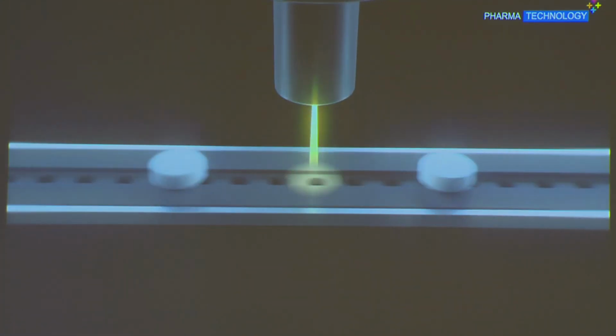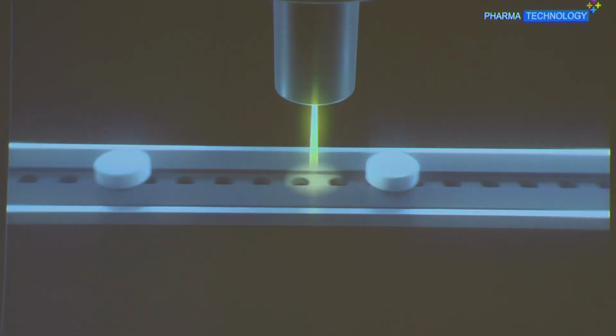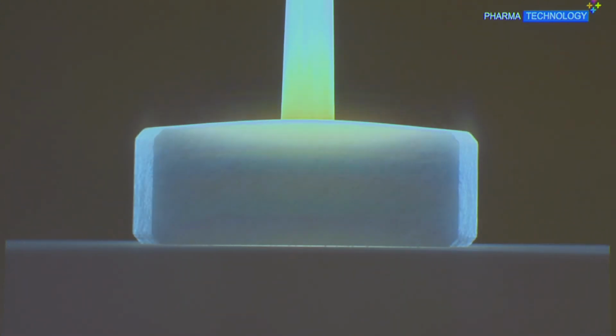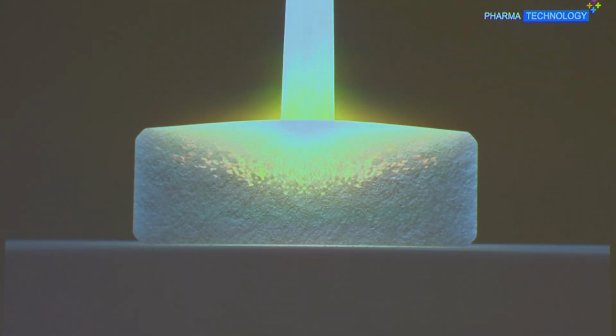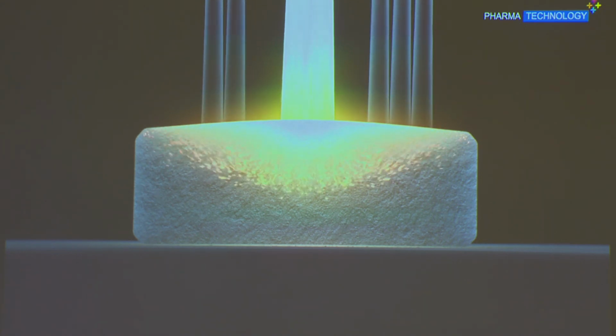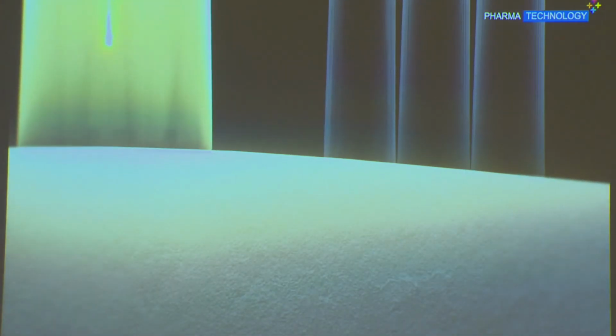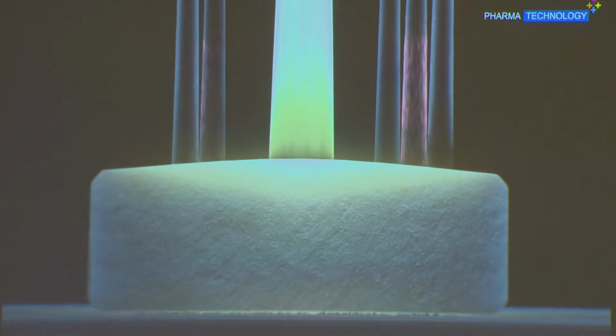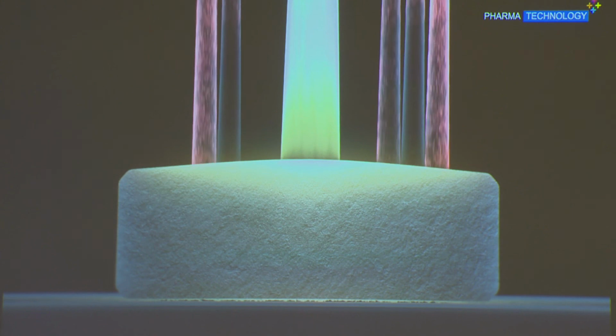Then, the product enters the NIR SRS measuring chamber, where the NIR infrared beam penetrates the surface of the tablet and collects spectral information about the API. The re-emitted light is picked up by 9 optical fibers and transmitted to the spectrometer. The obtained spectra are converted into an API fraction with the use of a chemometric model.